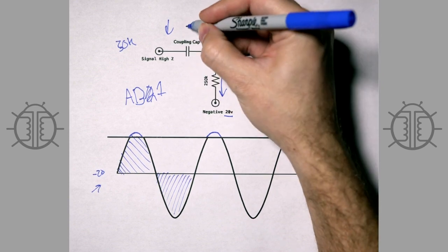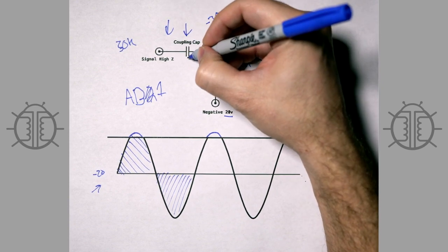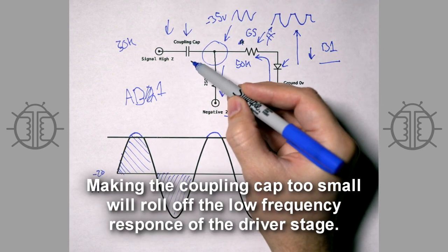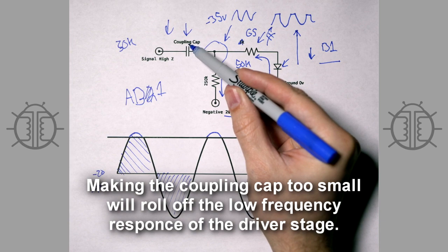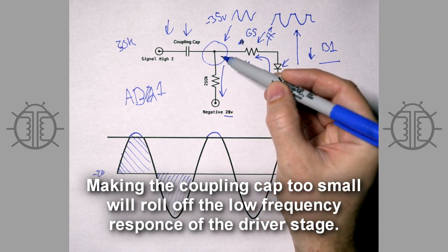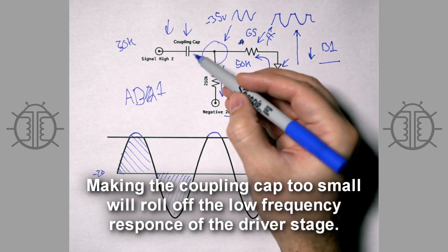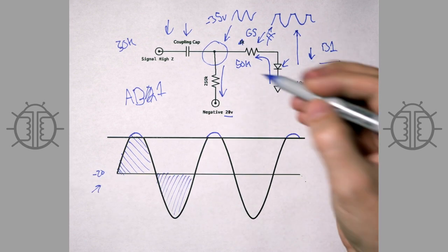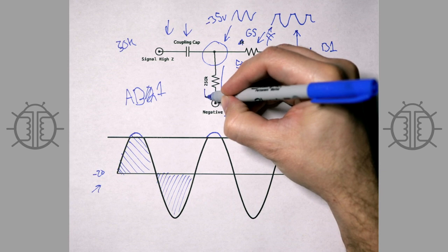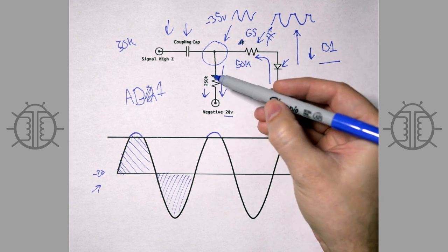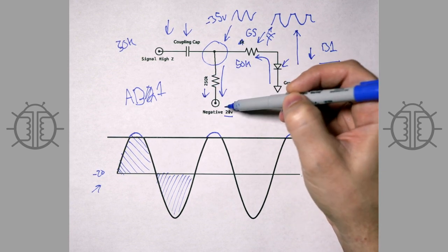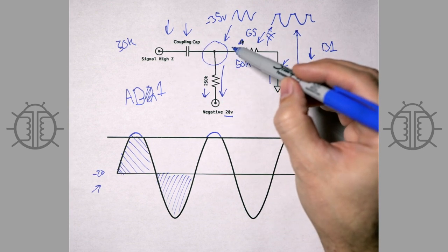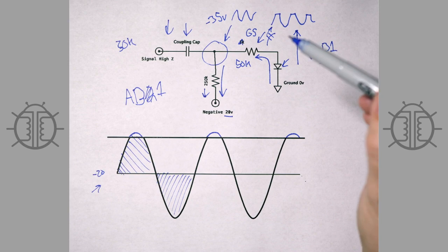Another thing that some people do is they will take the value of this capacitor and make it smaller, in the hopes of decreasing the time constant between this value and this value so that the amp recovers from blocking more quickly. Or you could take this value and make it smaller, and what that does is it allows the electrons to discharge more quickly, thereby decreasing the time constant of the circuit again, making it recover more quickly.